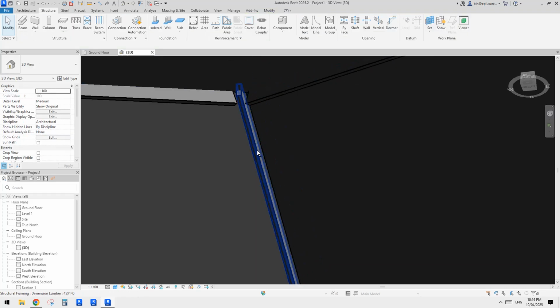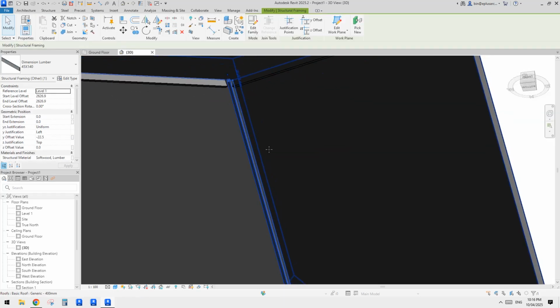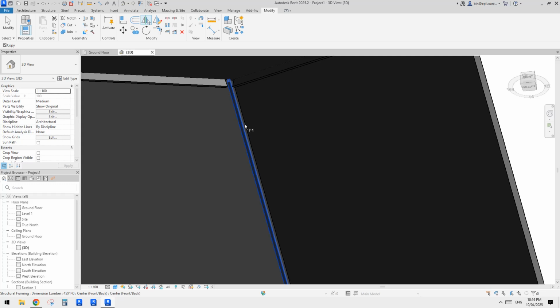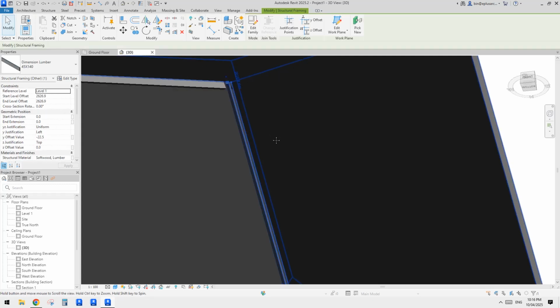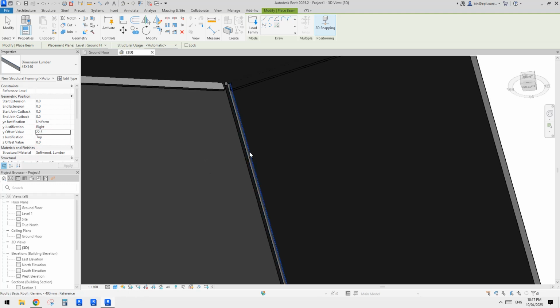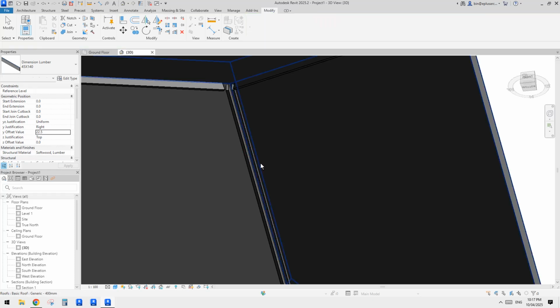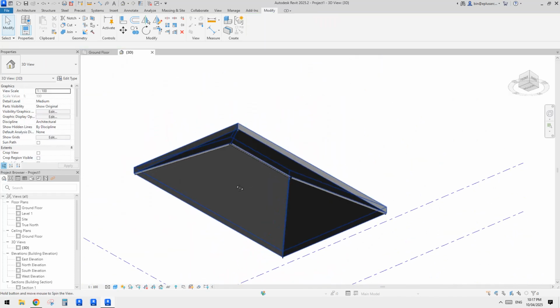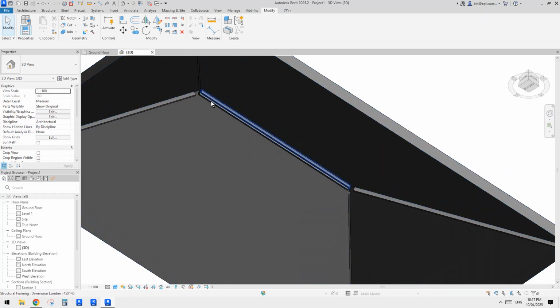And then once we have this one, one option is we can probably just mirror this. Looks like we can, so we can just place another one. So maybe, okay, I'll just use CS, create similar again, pick line. This time I'll change this one to right, and with the positive 22.5, I'll pick this line again, and you can see we have another one. So yeah, that's 1, 2, 3, 4.